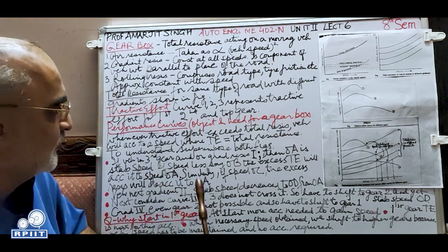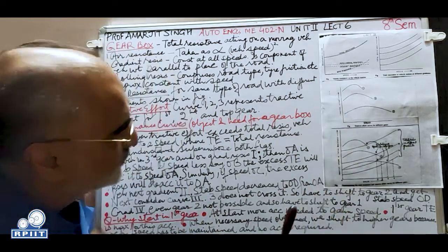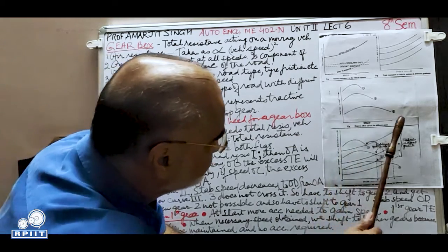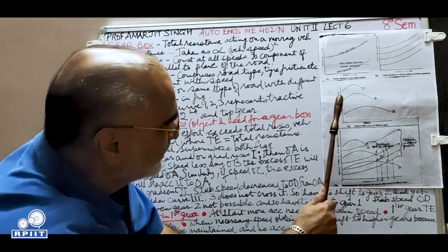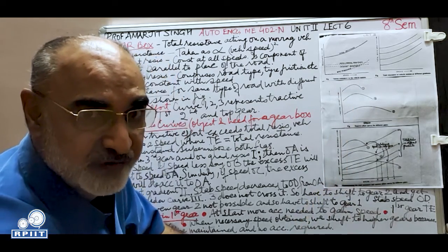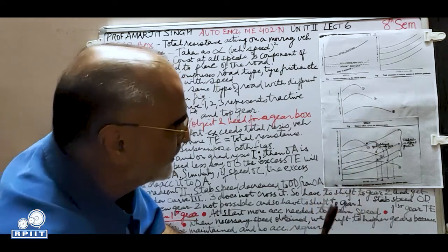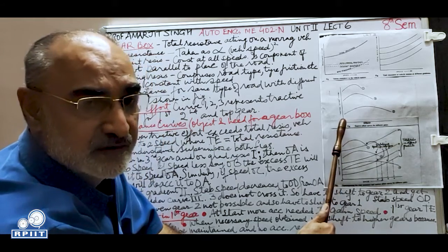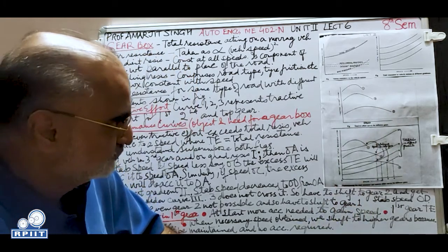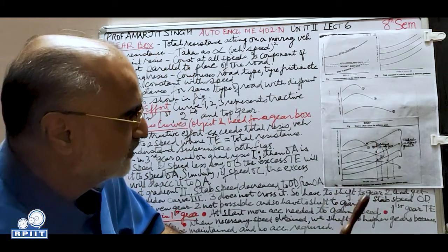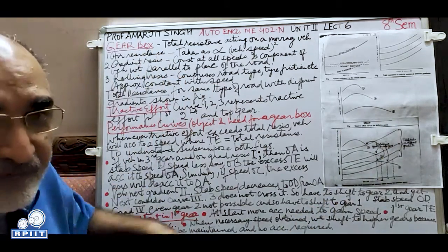And so tractive effort is represented by the curves. This is tractive effort and this is the speed. The tractive effort, as I said, is provided by the gears. Maximum is for the first gear, you have to start the vehicle from the rest. This is the second gear, number 2 it's mentioned. And let's say it's a 3-gear vehicle. This is the third gear. The least tractive effort is the third gear, because you just want to keep the vehicle in motion at that time.